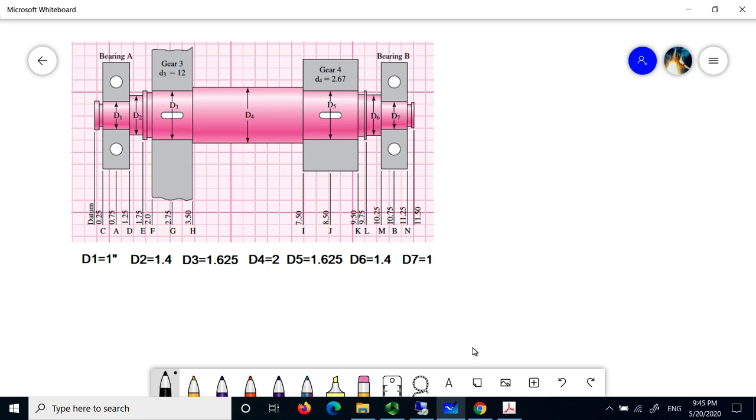Now I'm going to model this using ANSYS, and at the end we are going to compare it with hand calculation. As I said in class, in FEA analysis we usually try to eliminate features that are not going to affect our results much, to make the modeling easier. In hand calculation, the same thing happens: we make simplifying assumptions.